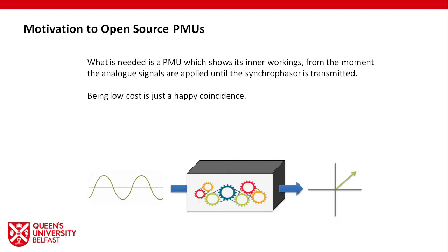What I needed was a PMU which showed its inner workings, from the moment the analog signals are applied until the synchrophasor is transmitted. I needed a device where the full process that all the data goes through from beginning to end is fully understandable and fully transparent. That was my original motivation behind creating an open source instrument, OpenPMU. The fact that it ended up being a low-cost device was just a happy coincidence. It was not the original design goal.